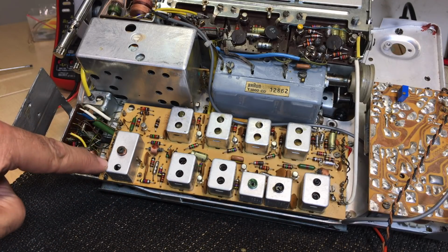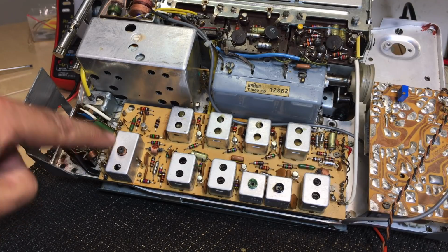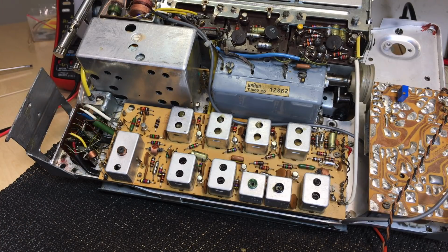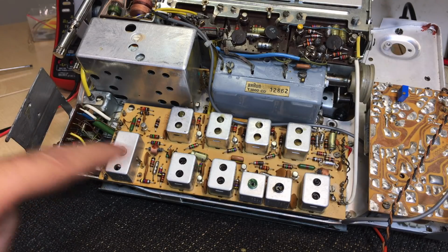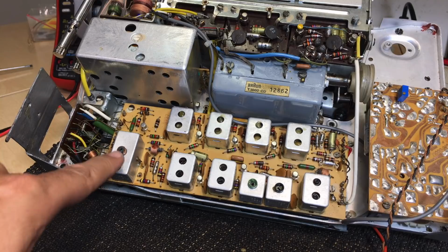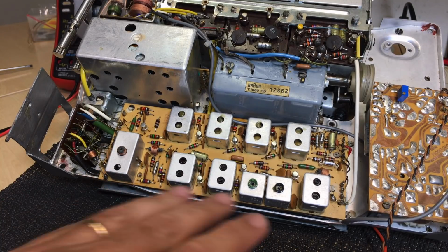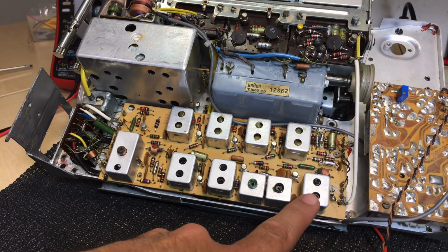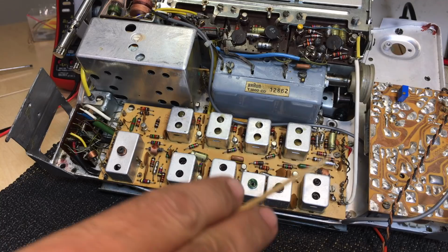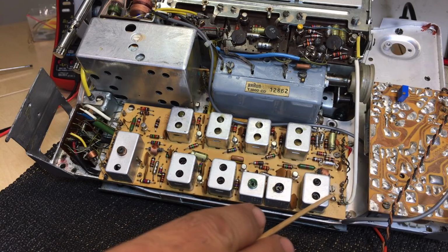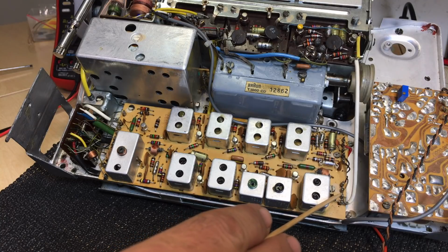So this thing should produce a 455 kilohertz carrier frequency, a sine wave, as clean a sine wave as possible. And it should be very stable. And you should be able to adjust it by a few kilohertz one way or the other with that core. The way to adjust it is you feed in the carrier, just like we did with the normal alignments over here. But you don't modulate the carrier. You feed in just the carrier, 455 kilohertz, and that's a carrier wave with no audio modulation on it.